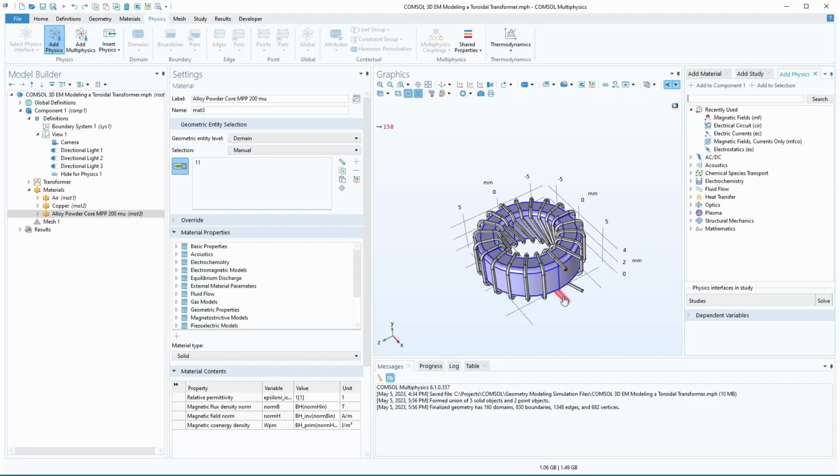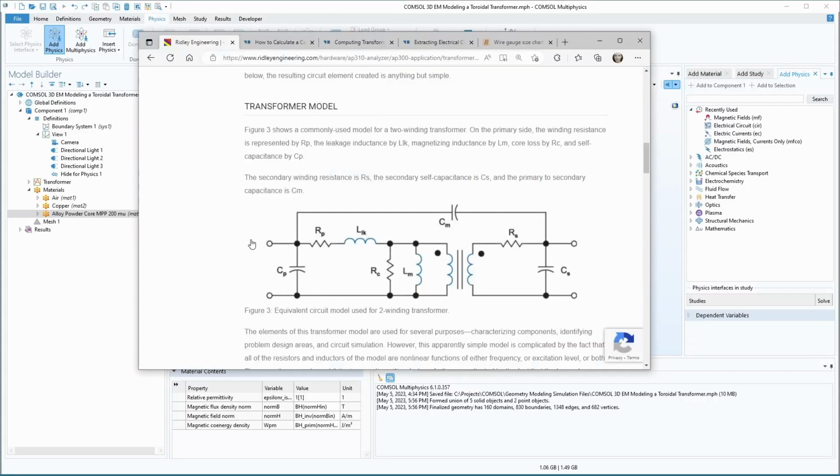So when you connect a signal up here to the primary, you measure the inductance with the secondary open and shorted. When you connect the signal up here and have this side open, then this side is not really doing a whole lot. So you're measuring this LM right here. And then when you short this side, that's kind of canceling out this LM. So then when you measure here, you're measuring this leakage.